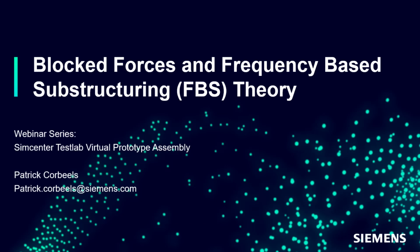As Charles has mentioned, this part will be a bit about the methods that run behind VPA that enable this system NVH prediction. So the big focus there is how to characterize independently these sources, so there are quantities in place like blocked forces and so on, and also how can I then, once I have characterized these sources, how can I do predictions? So that's where frequency-based substructuring comes in.